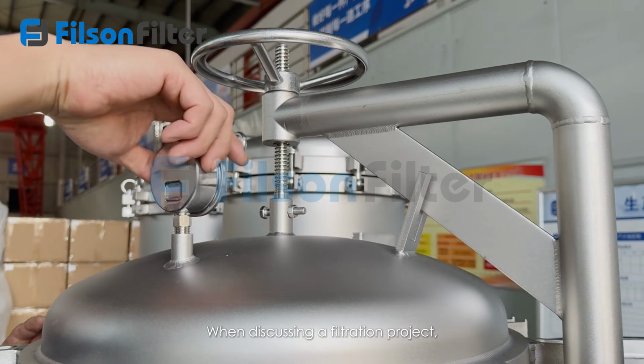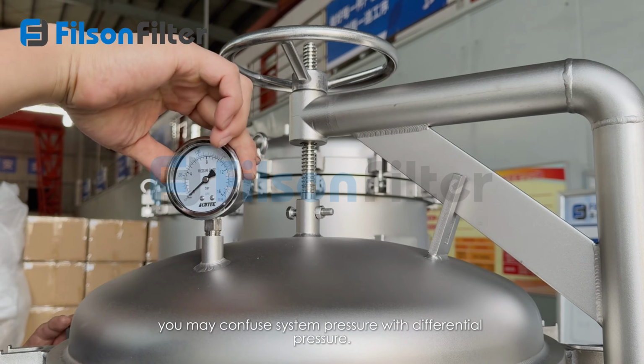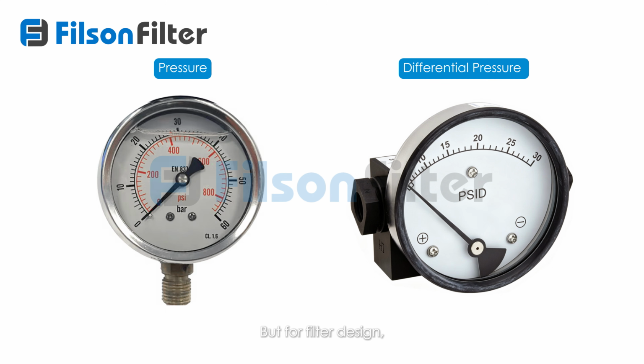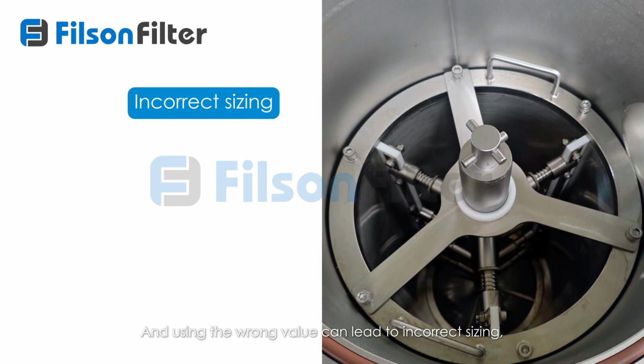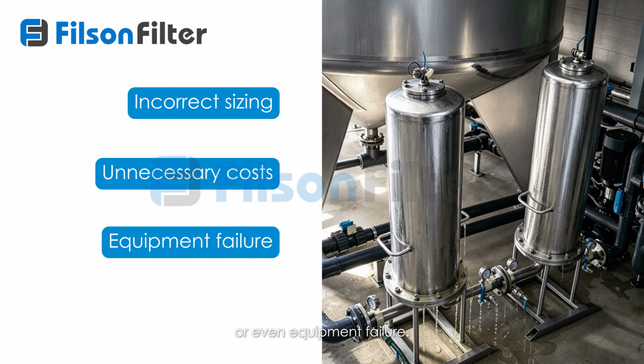When discussing a filtration project, you may confuse system pressure with differential pressure. At first glance, they may sound similar, but for filter design, they mean completely different things. And using the wrong value can lead to incorrect sizing, unnecessary costs, or even equipment failure.